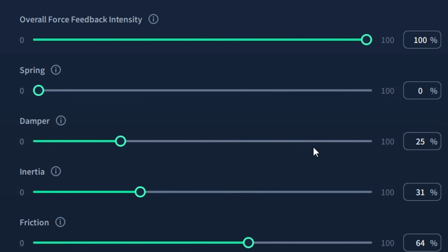We start with the damper, which adds physical resistance on the speed of your control inputs. If you yank the stick quickly, it fights back. If you move it slowly, it's completely fluid. For the Cessna 172, keep this low, between 30 to 50%. A 172 stick is light and responsive; too much damping makes it feel sluggish. For the Airbus A320, crank this up to 40 to 60%. This stops the stick from feeling springy and prevents you from over-controlling and oscillating past your target pitch on short final.